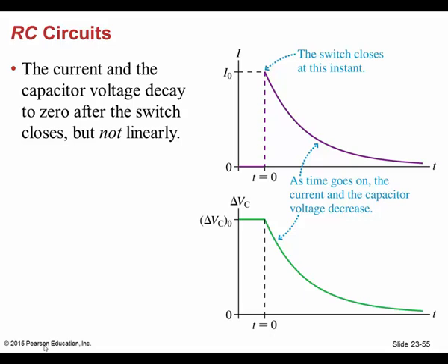All right, now look, here's how we look at it graphically. Now, this is for a discharging capacitor, not a charging, but a discharging capacitor. Notice that as soon as the switch closes, notice what happens to current. You have max current at I0, okay? And then it decreases down to real close to zero, okay? All right, same thing with voltage. Notice that you have maximum voltage, and notice how it decreases.